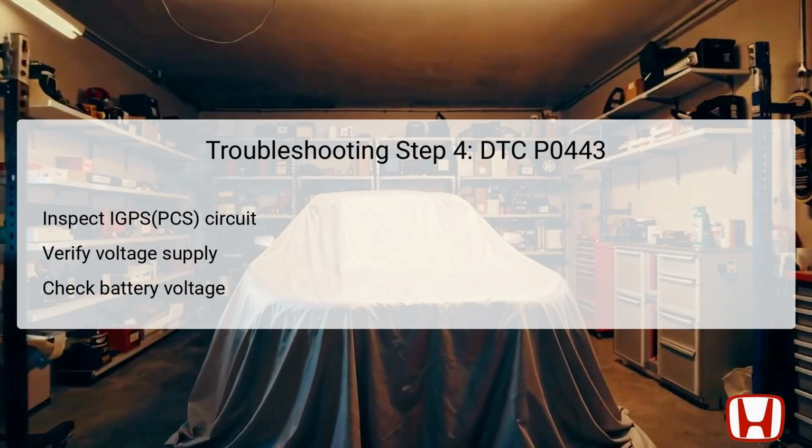If this voltage is absent or significantly lower, it suggests an issue within the circuit itself, which can range from damaged wiring to blown fuses. These details are essential in narrowing down the root cause of the DTC P0443 malfunction.